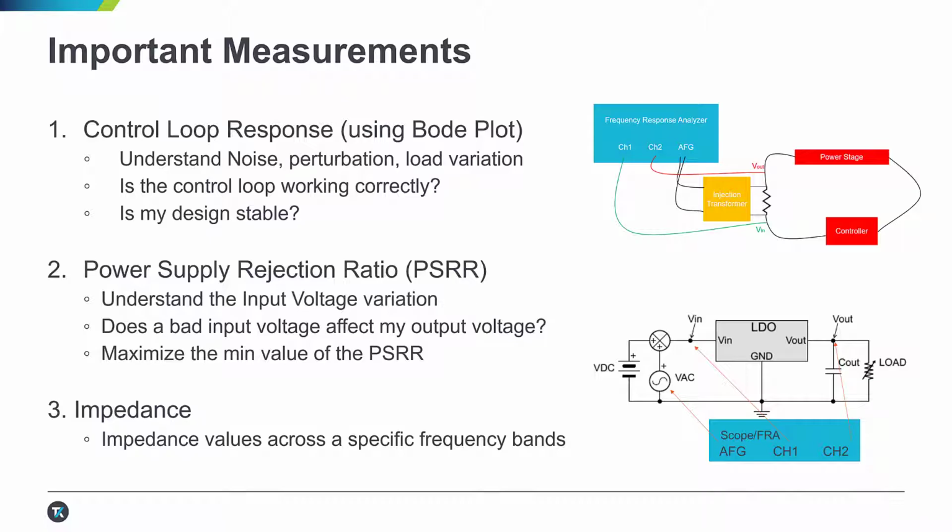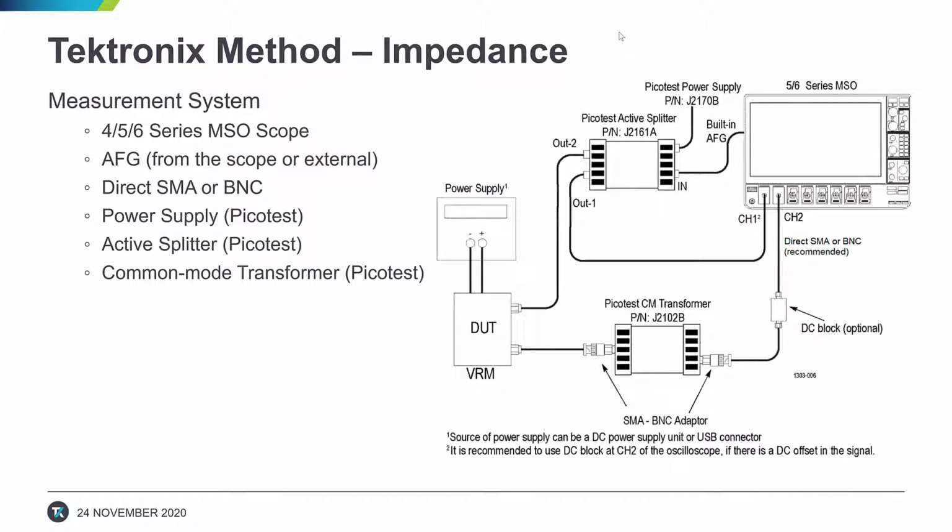So the oscilloscope-based method that we use within our power measurement analysis software can measure down to as low as 1 hertz, so right around the DC value that you would expect an oscilloscope to measure to. And thanks to the use of components like spectrum view built into our oscilloscope, we can measure very, very low noise type of systems, and that allows us to achieve very, very small impedance measurements down below 1 milliohm type of values. So this is a setup for our final demonstration today.